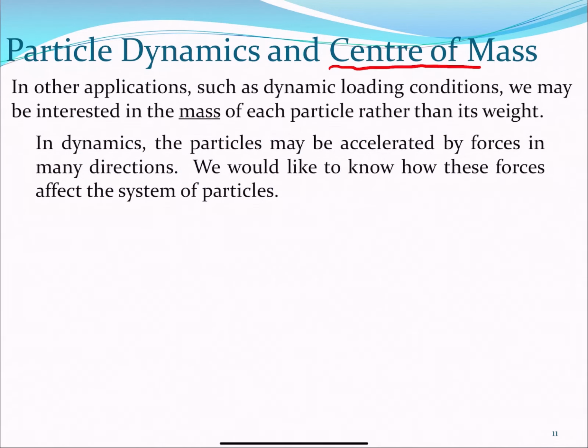We just dealt with the center of weight. For the center of mass, if you are located on the Earth, the gravity is pretty much uniform among all bodies. So the center of gravity will be equal to the center of mass, because weight is equal to mass times gravity, if the gravity is the same for all the particles in your rigid body. It doesn't matter what the gravity is.